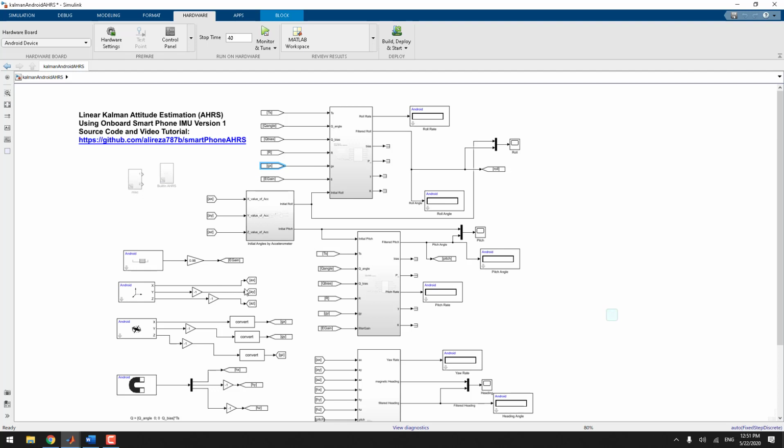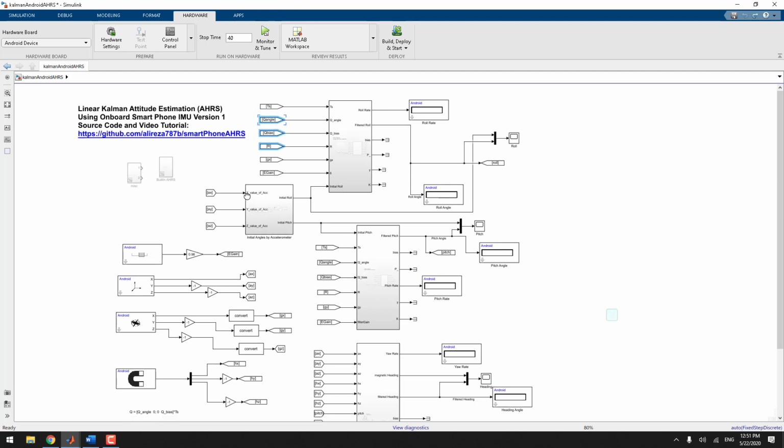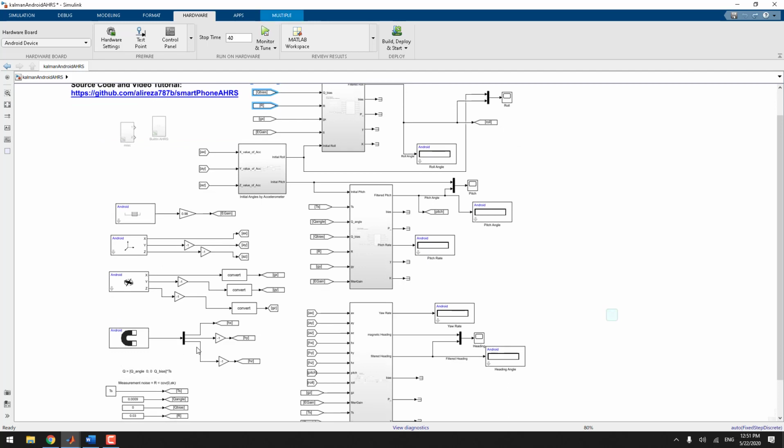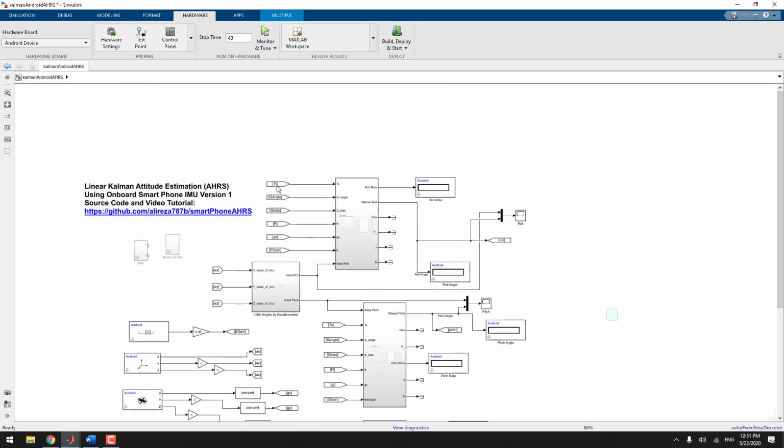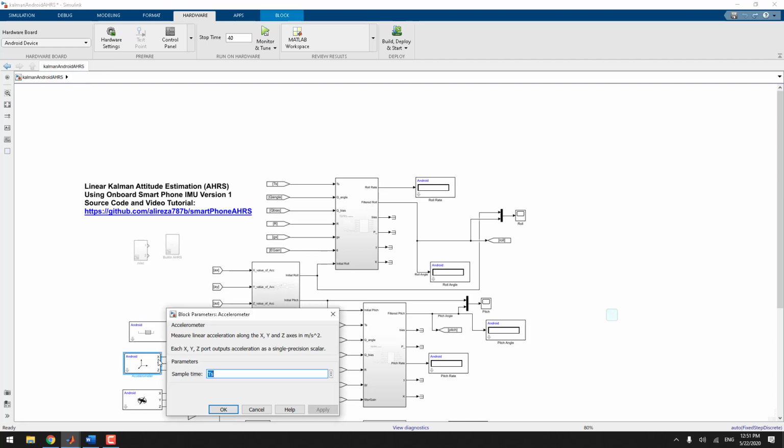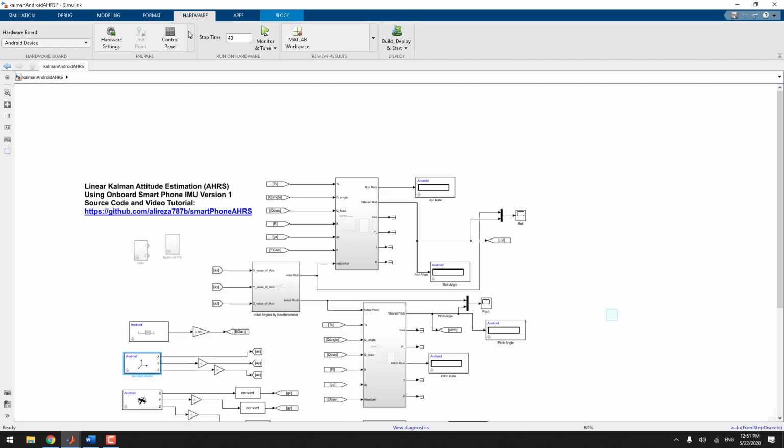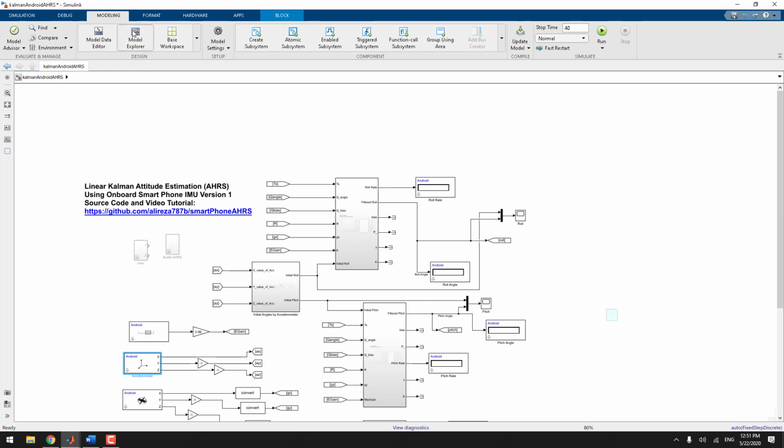Which gyro? The first block is for the roll angle, and for roll angle, you know that we need the gyro around the x-axis. And the other ones that you can see, such as R, covariance, bias, X, and other stuff, the theoretical part is about the Kalman filters. I'm not going to go through that, and I'm not a mathematical expert. I'm just using the code that I found from the internet. And the T of S is the sample time. I have set the sample times for the code in the settings.